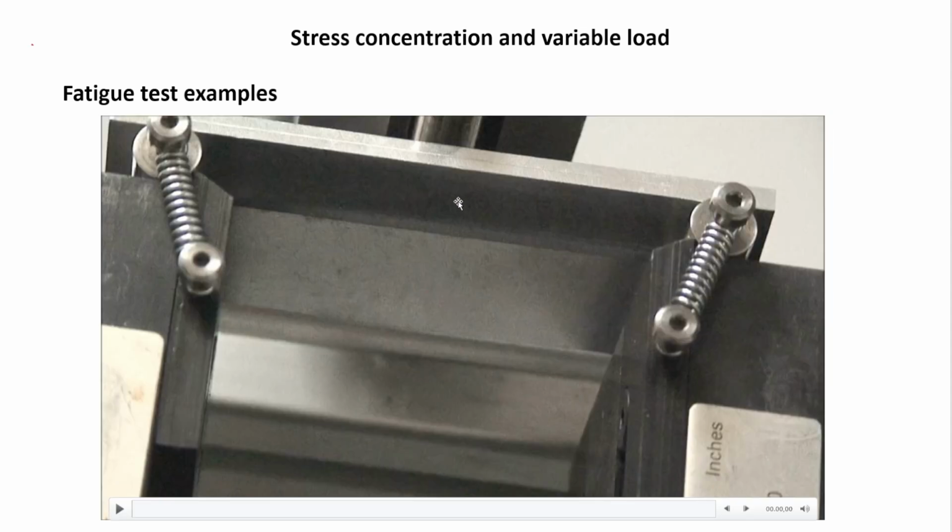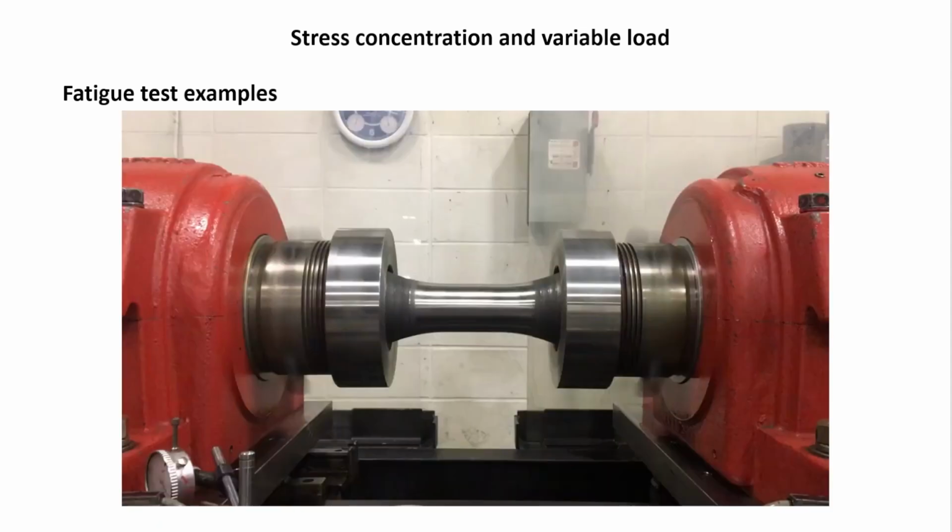Now this is just a simple bending moment applied to this beam, meaning you just apply lateral forces to the beam and then release the force. Apply lateral forces and release the force. Now this other part is a little bit different because this is a rotating shaft, and this shaft is subjected to reverse bending. When I say reverse bending, it's that these two motors you have here, or one motor, one driven and one driver, are not exactly aligned, but a little bit misaligned, inducing some bending on this shaft here. And let's see what happens when you start.